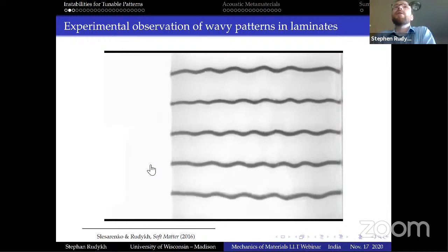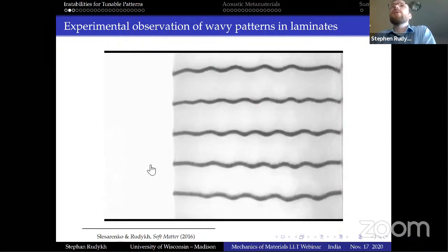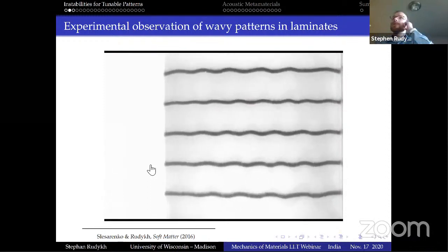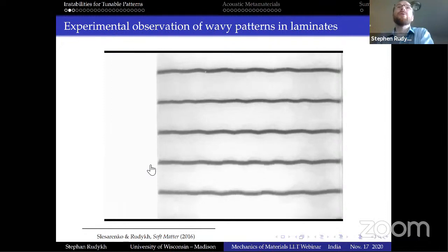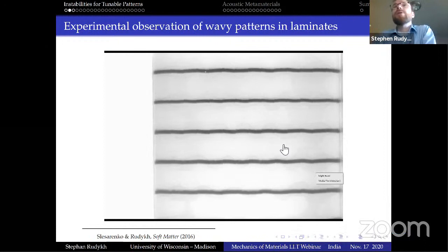We'll see this a little bit on the right, almost in real dynamics, but of course it's quasi-static, it's very slow. So we try to kill the viscoelastic behavior for this, and we'll explain why very soon. Again, this is the formation of this wave pattern that can be very accurately predicted by the theoretical analysis and by numerical simulations.